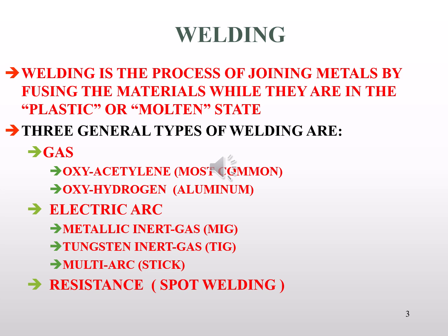Another common question is, what are the most common gases used in gas welding? Well, oxyacetylene, oxygen and acetylene are combined for the majority of all gas welding work that will be done. In some cases, they'll use hydrogen as a fuel gas when they're doing aluminum welding because hydrogen contains no carbon and aluminum does not benefit whatsoever from additional carbon being added to it.